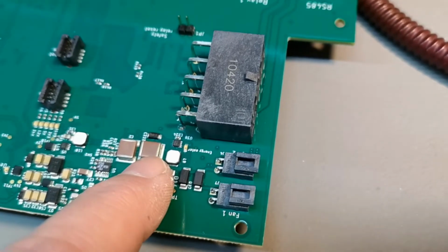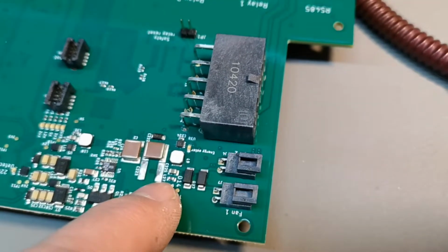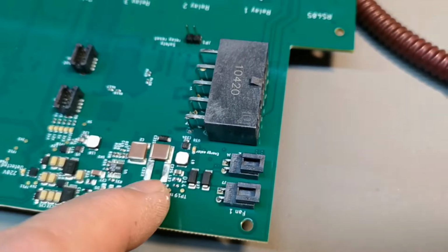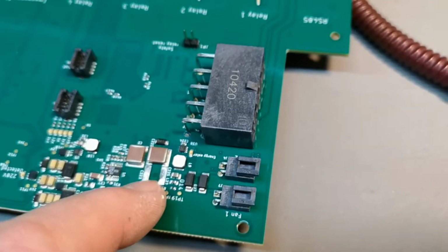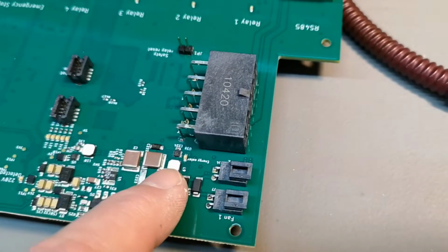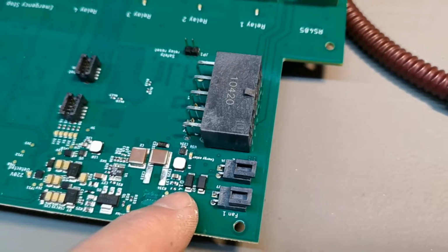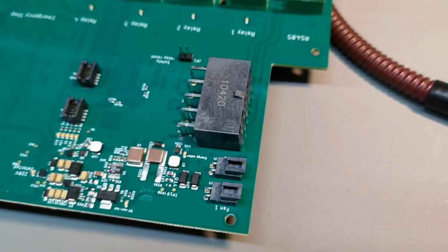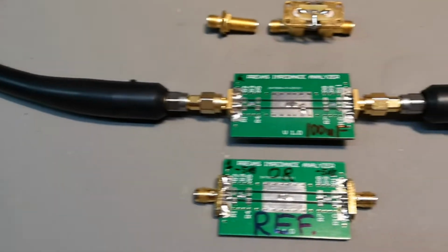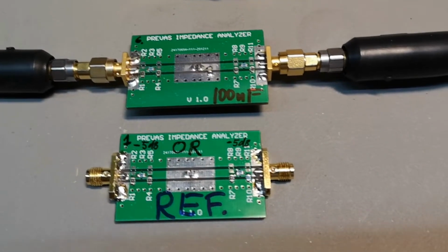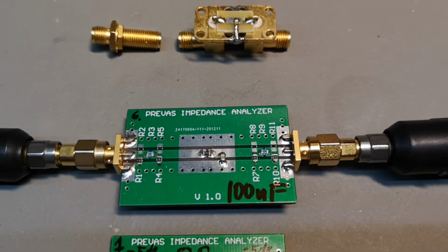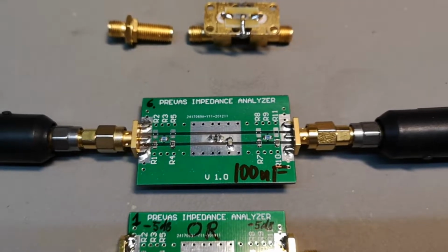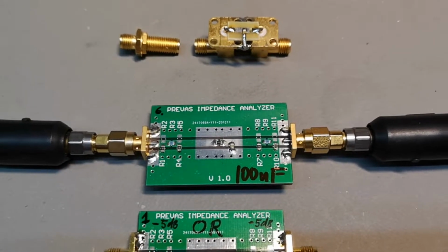So if we had tested not just the component itself, but the way that they interact with each other, with the wires, we would have seen that we had a really big resonant problem at the harmonics of this converter. So how do we measure the impedance of a capacitor, for example, without affecting the capacitor and creating a new resonance?